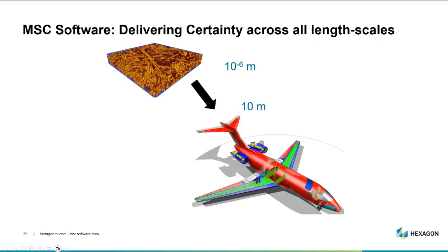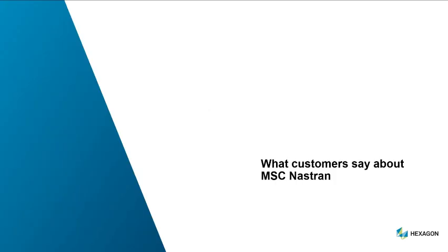And that can be done simultaneously. It can also be staggered, where we just calculate it and transfer it across and use it as a stiffness. But for the case where I want to see how this behaves as fibers start to fail or the resin starts to fail, I can even include that in this simultaneous simulation, where we microscopically and macroscopically solve the behavior of some kind of a structure at the same time.